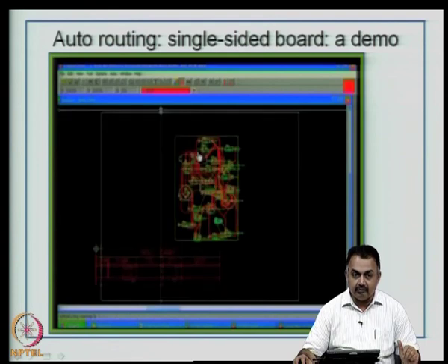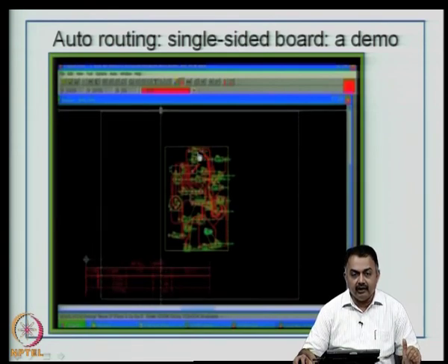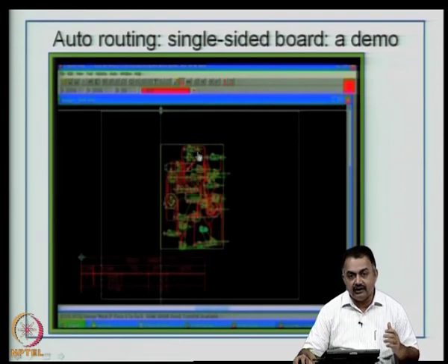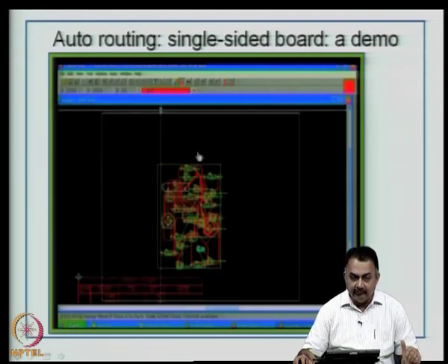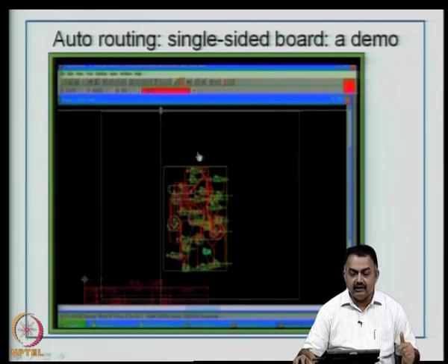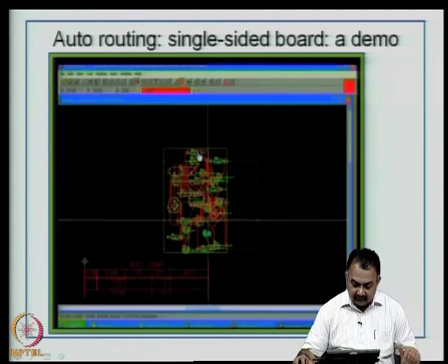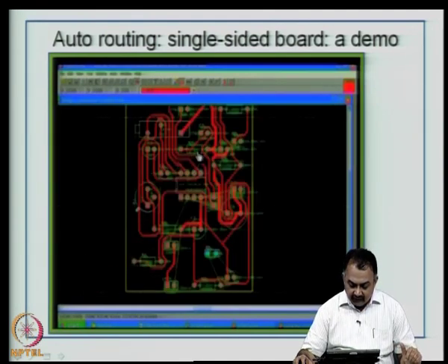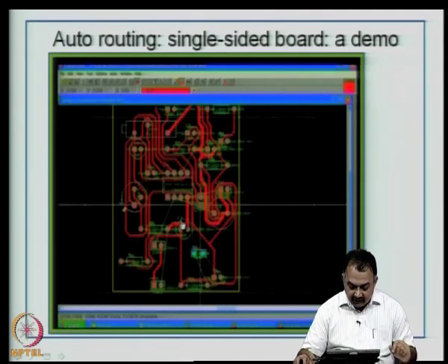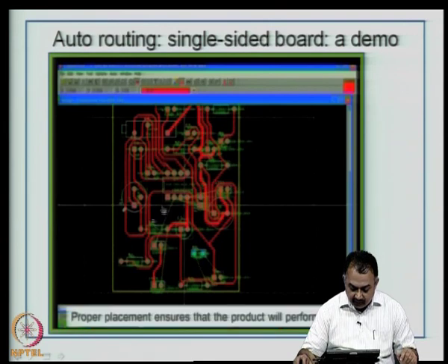You can also expect a few percentages of nets not being completed at all, because the distance of the components is longer. Some of the nets act as obstacles, some of the packages act as obstacles. So, as you can see here very carefully, some of the nets are not routed. For example, this is an unrouted net, this is an unrouted net, now this is an unrouted net.